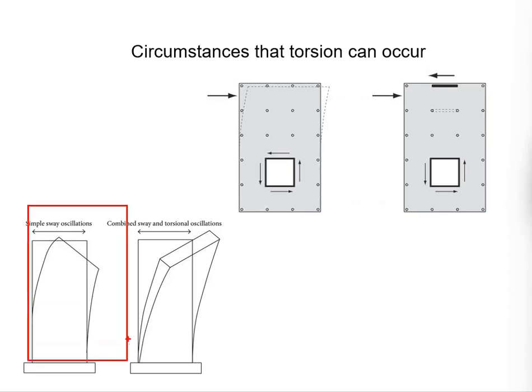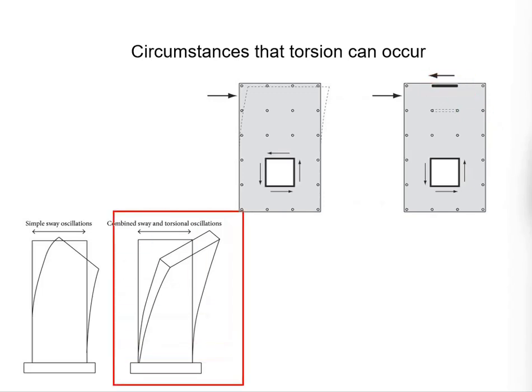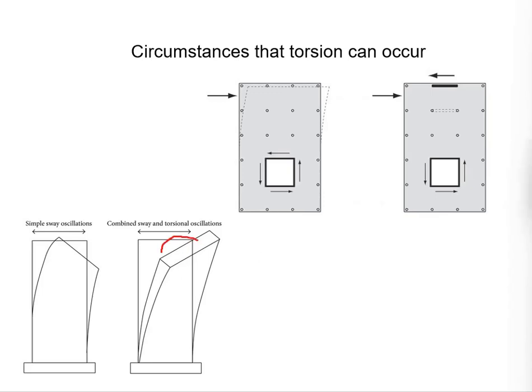This is only valid when you are combining the wall in two different perpendicular directions. Imagine you don't have this, and you have the shear wall to resist the force alone. Very likely it will end up to be something like this, as the deformations tend to go to a weaker direction. This leads to torsional response of the member.